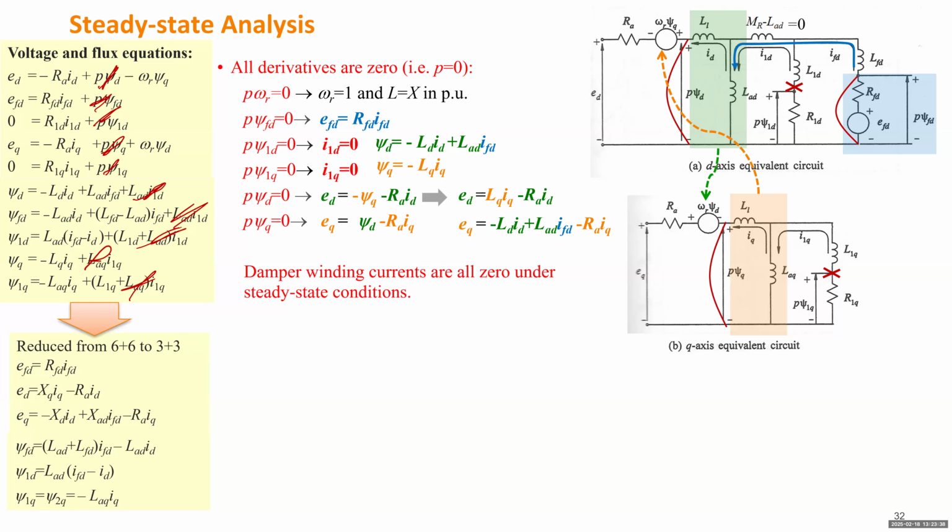Okay. So then we just get rid of any item which has become 0. So we will have a new set of equations. And there's some equation which doesn't have, let's start from 0 on the left-hand side. We simply get rid of, oh yeah, this one also needs to be gotten rid of. So that equation is removed. This one is also 0, this is all 0. Yeah, that's pretty much everything. Okay. So now we only have 3 voltage equations and 3 flux linkage equations.